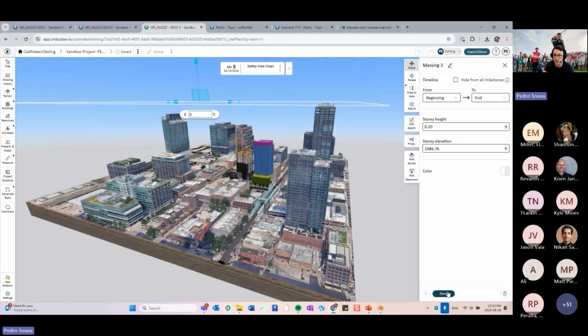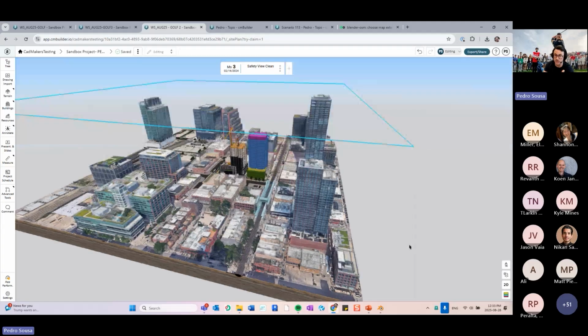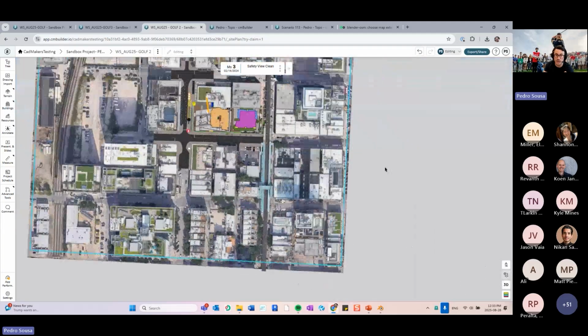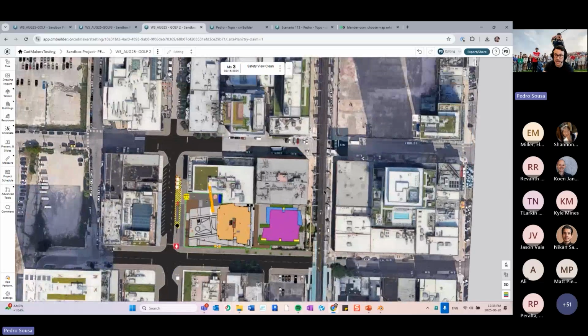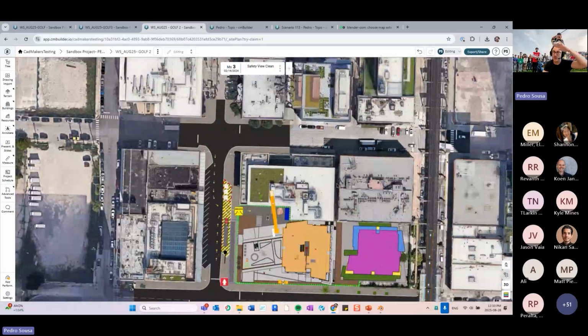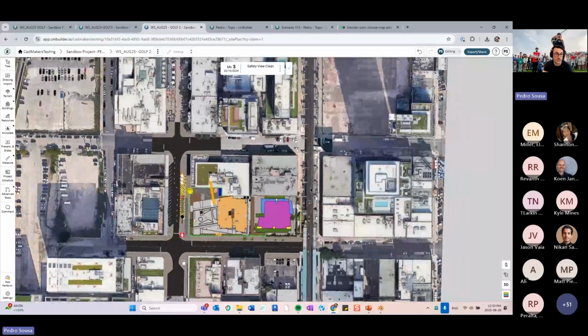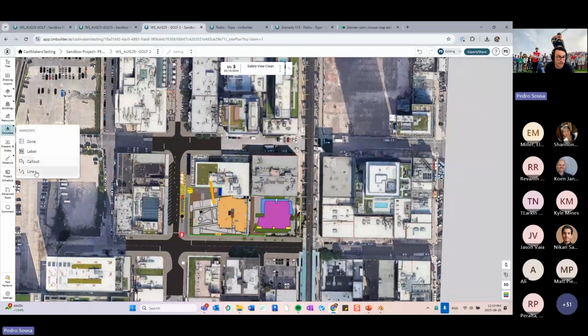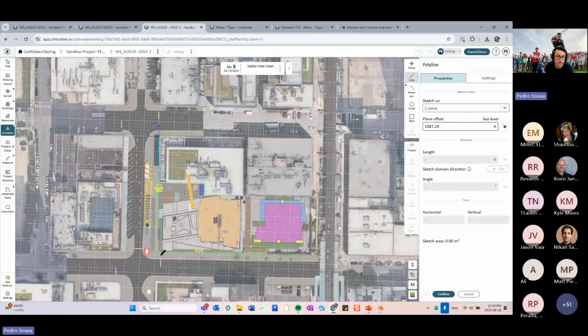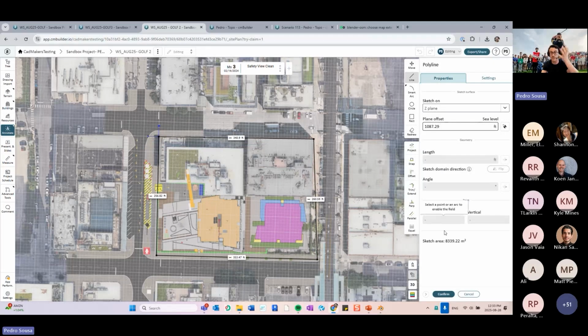So if I'm working on a 2D view to identify elements of the 2D view, now if I go into 2D, every time I place a sketch or an element, it will be placed on top of that massing, right? So if I go here and I annotate and draw a line, just any line, you might think that you're selecting the point on the ground, but as you can see over here, my plane offset is showing that I'm drawing something really far up on the view.